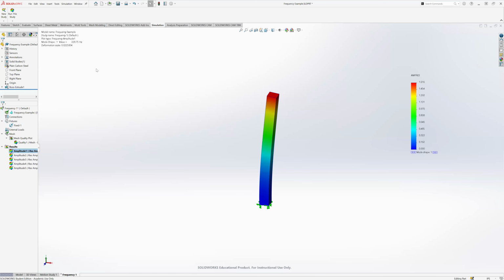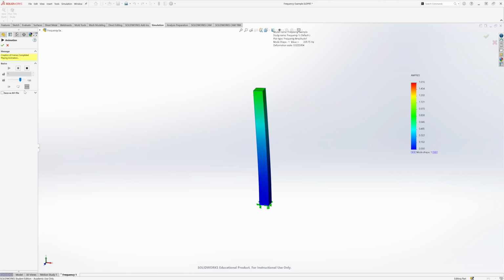So what we're going to look at here is it also tells you the hertz. In this case, this specific mode shape, which is what they're called, different modes of vibration, occurs at 228 hertz. I like to always animate these to actually see what is going on at the corner. Another thing, a lot of times I stop this and up the frames to like 15, so it's a little bit smoother of a plot. So you can see how it's behaving, which is really nice.